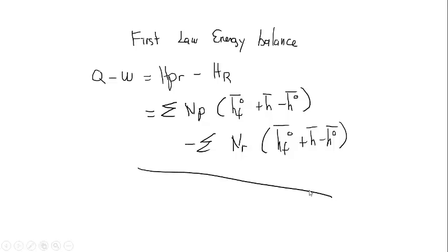This would be a first law analysis. That would be for the sum total of the number of moles of a particular product times the enthalpy of that product, right? The enthalpy being enthalpy of formation plus the sensible enthalpy minus the reference state.